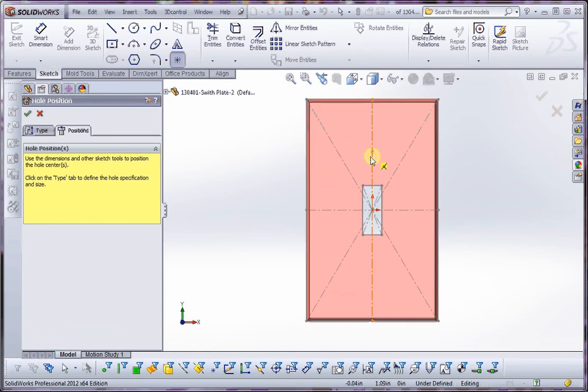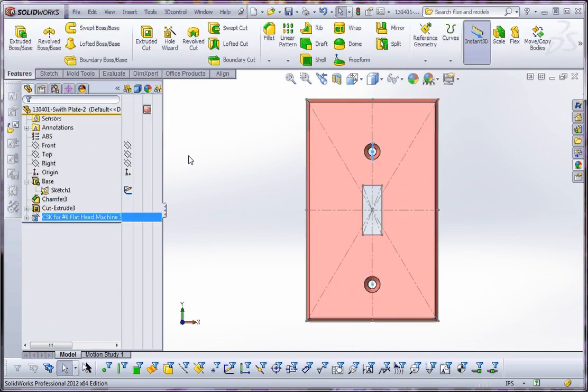And if we go normal to, as opposed to being sideways like that, we can actually select that geometry. So now you see, as I take that little pencil icon as part of my cursor over here, and rest it over that point, it's going to establish a coincident relationship with that. You can see the preview of the coincident relationship. And we do the same thing on the bottom and aim down there. So let's exaggerate that a little bit and just put off the line and go to the green check mark.